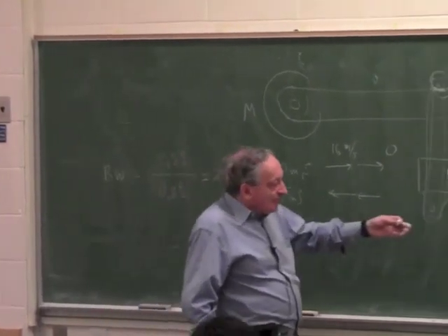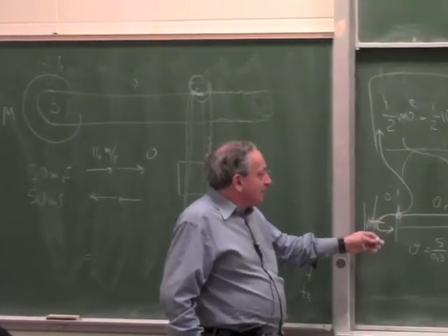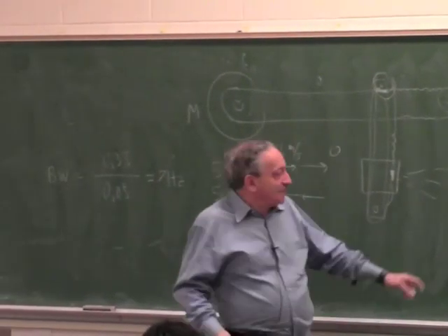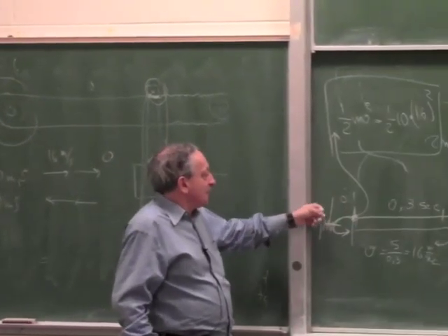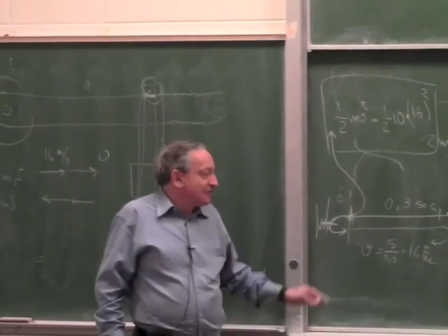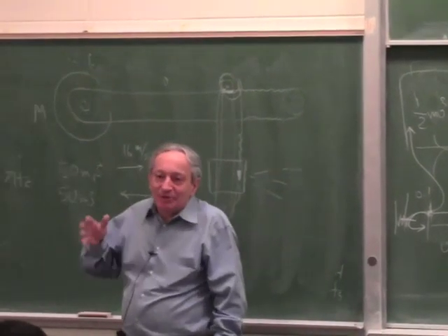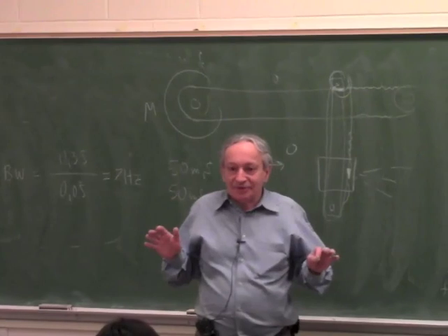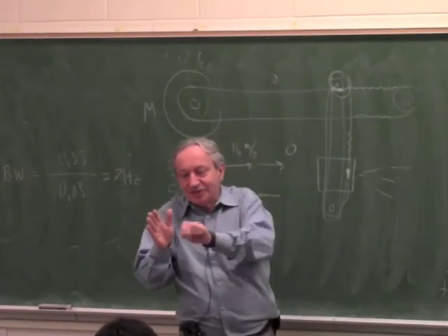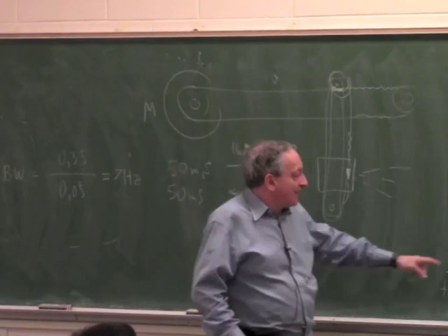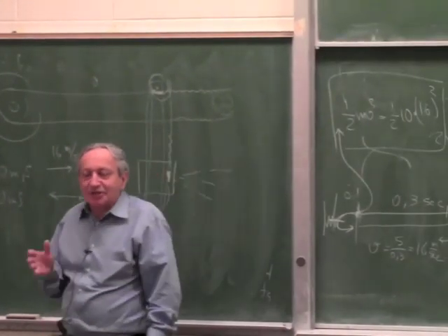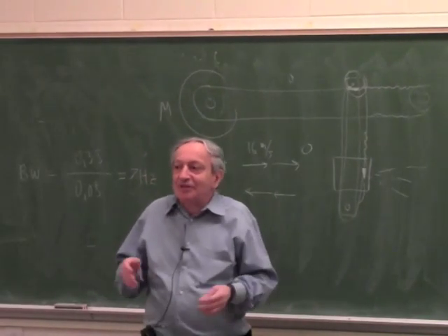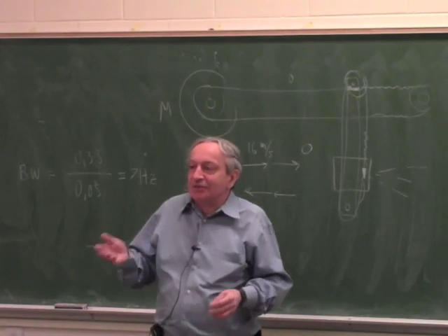There is actually a simple way to do regenerative braking. So the power you need is just maybe 20% of the energy. We said the energy here, you have to dissipate 1300 joule and then input 1300 joule. But if you have some kind of a spring or a bumper, maybe you assume 20% of that would be enough. Because if it was frictionless, you would need 0. Because frictionless, the spring will absorb all the energy at the end of the travel and output it all back, come back to this velocity. So when you say how much energy do I need, you just make a guess. You say, well, it's not frictionless, it's not perfect. Maybe 10-20% of the stored energy is still wasted.